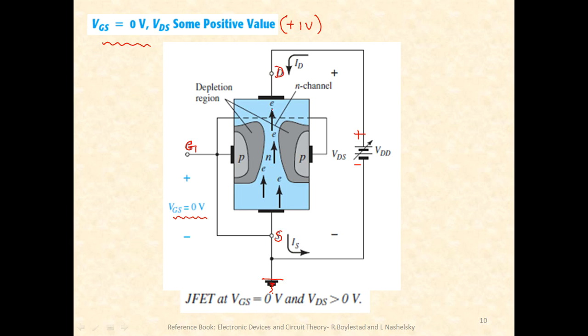Okay, so what happens in the last session we had seen that this PN junction, due to the applied polarity, gets reverse biased. Okay, because the drain region, which is of N type, is being applied a positive voltage, whereas the gate, which is of P type, is being applied a relatively negative potential when compared to the drain end. So obviously we can say that, just highlight it here, so this portion becomes reverse biased.